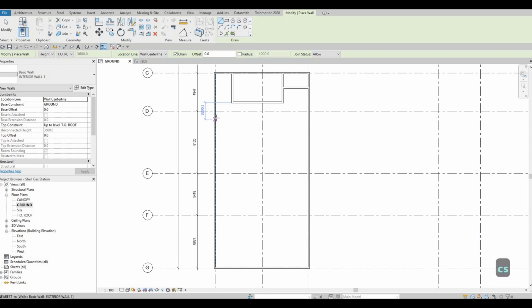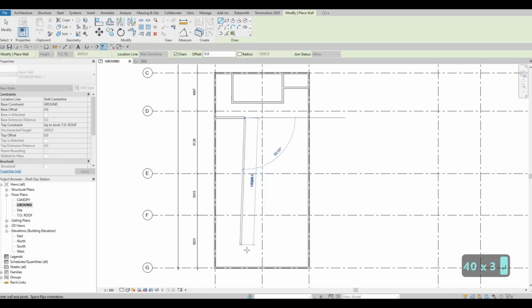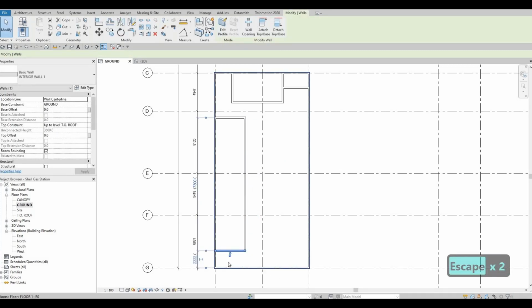This is showing around 2000 from this area, and then I would like to put this one around 4000 from the wall. So you could type in 4000, and then here we could just close this off, and we wanna maintain some aisle here so that we could exit as well.